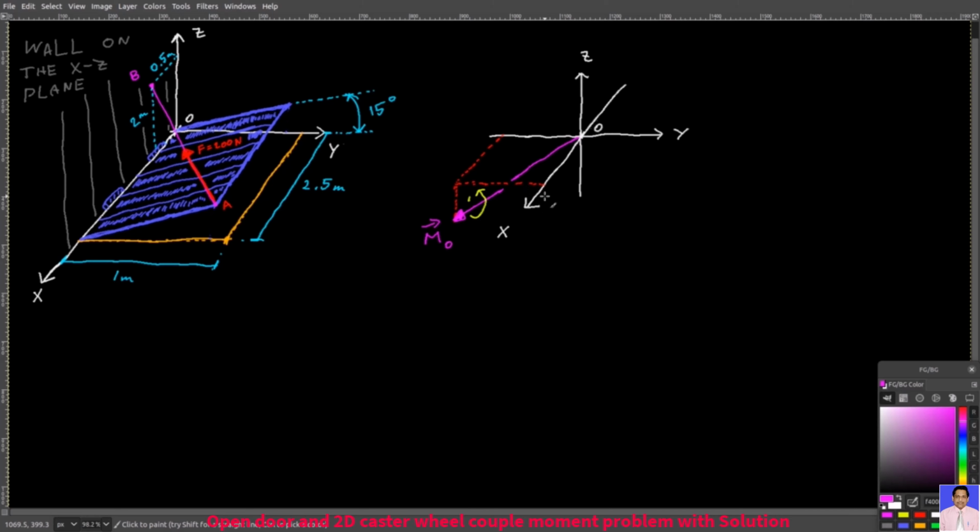However, it's not that useful to me because the door can only move about the x-axis. And that said, you can see the two hinges here. So I'm more interested in finding the component of the general moment vector in the x direction, which would be something like this. So that's what you need to compute, the component of MO along the x dimension.